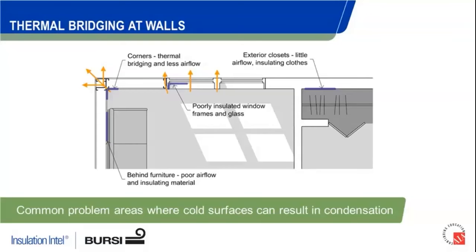And if that wall's not able to dry back out or warm back up and compensate for that condensation, then we risk potential for mold, potential for rot, structural degradation, and interior air quality problems as well. So if you have thermal bridging occurring, these tend to be some of the areas where it can be significant enough to actually start causing indoor air quality problems.